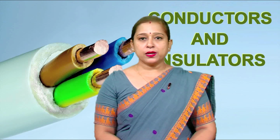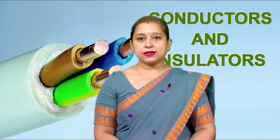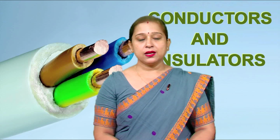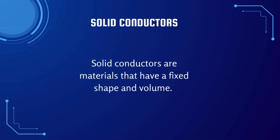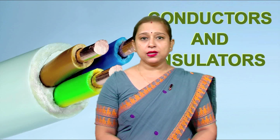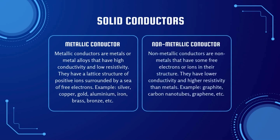Electrical conductors can also be classified on the basis of their physical state and composition. Here are some examples of electrical conductors in different categories. For example, in case of solid conductors, the materials that we use have a fixed shape and a volume. They can be further divided into metallic and non-metallic conductors. Metallic conductors are metals or metal alloys that have high conductivity and low resistivity. They have a lattice structure of positive ions surrounded by a sea of free electrons. Some of the metallic conductors are silver, copper, gold, aluminium, iron, brass, bronze, etc.